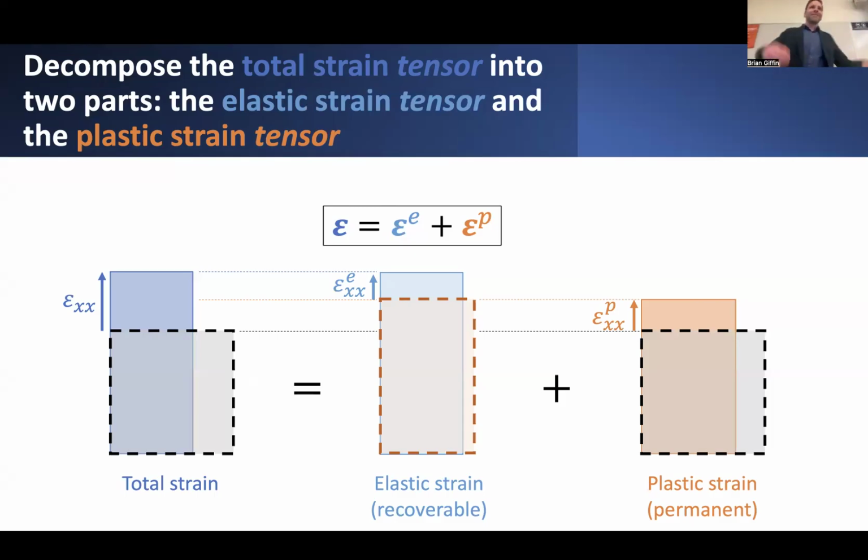And you could measure then the resulting permanent strain, or plastic strain, that occurred in this chunk of material. It might look something like this, where not only does it look like it's stretched out vertically, it may have also contracted inward. So in general, when we're talking about permanent strains or plastic strains, these deformations don't just have an axial component, they also have some lateral components of strain. We'll discuss a little bit about that in a moment.